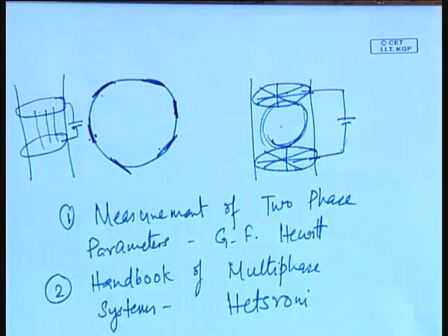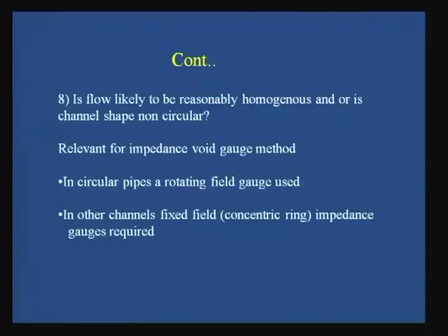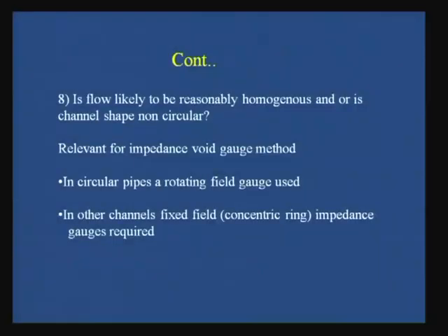Well, so with this we conclude the void fraction measurements. We find out that in void fraction measurements, the most important three techniques are volume measurement, radiation attenuation techniques, which can be absorption, it can be scattering to some extent, it can be emission of a consequent radiation, and impedance gauges.